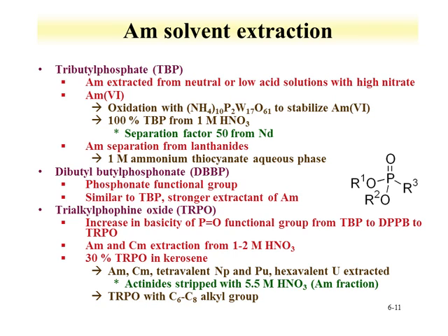The fundamental chemistry that we just described on americium can be useful for separations. As we know, solvent extractions are useful separation techniques, with tributyl phosphate being a major workhorse in the nuclear fuel cycle. We know that in high acid concentrations, americium does not separate. However, in neutral or low acidic solutions with high nitrate, tributyl phosphate can be used to extract americium into the organic phase.